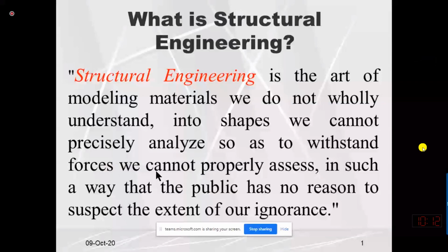And what we do then is compare the applied load effect. Applied load effect means the applied stresses, which may be bending stresses or shear stresses, against the material strength. So applied stress should be less than or equal to material strength. If so, then our steel structural shape will be good to carry all the load safely.